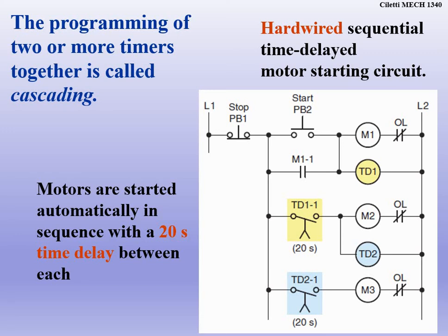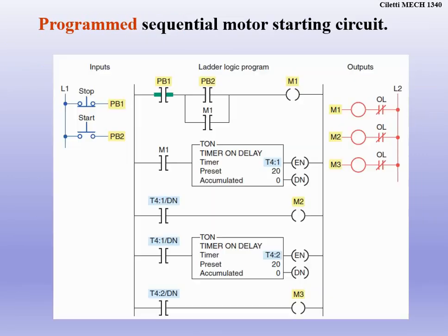We don't want a big inrush of current. If we have a bunch of motors that we want to start in a delayed sequence, we can start them up that way. Say we've got a bunch of cooling fans or something that need to turn on. We don't necessarily want to bring them all online at one time, right? There's a big inrush current. We can bring up one and have different types of delays in between those. We call that sequential motor starting. And it's really based on you and how you write your program for your timer, and how you set that up so that we can start motors with different time variances between all of them.